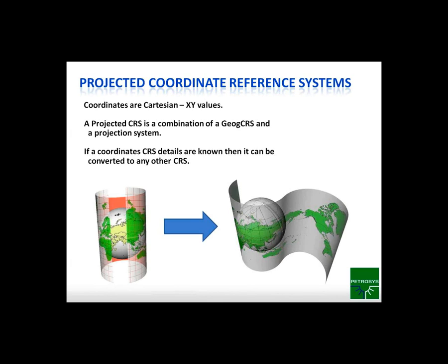And the way we do that is by taking that spheroid, and the way I like to imagine it is you wrap some sort of paper around it, and I have an illustration down at the bottom of how this kind of works. We're showing a cylindrical projection. What I like to think of it as is kind of like a piece of paper being wrapped around the spheroid in such a way that you don't have to deform the paper, and then you project. So you have some sort of light force within the spheroid. You project out so you can actually trace the edges of the continents, and you end up with some 2-dimensional representation of that 3D object.